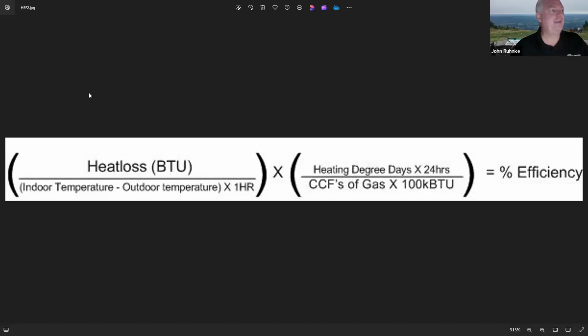I appreciate it. And also, if you're grabbing free energy from the air, you're not paying for energy from the air. You're not paying for energy from the sun. So I look at that as free energy, and thus we get over 100% efficiency. You're right, if you're thinking of it in engineering terms, someone could calculate how much energy is actually coming from the air and put a number on that. But I see it as free energy because no one's going to pay for it. So you put 100,000 BTUs into this heat pump, and you got 300,000 BTUs of energy feeding the house. So you're 300% efficient. That's how this efficiency number would look.